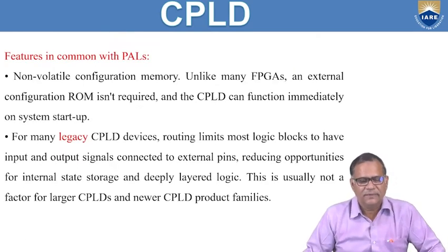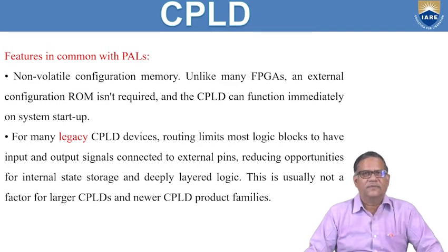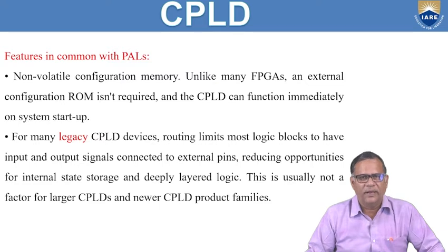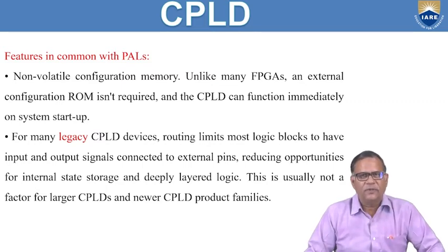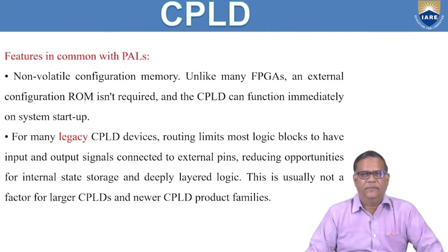Now let us discuss the common features of CPLDs with PALs. PAL is programmable array logic, which has a programmable AND plane and a fixed OR plane. So the feature which is common with PAL is that it has non-volatile configuration memory.